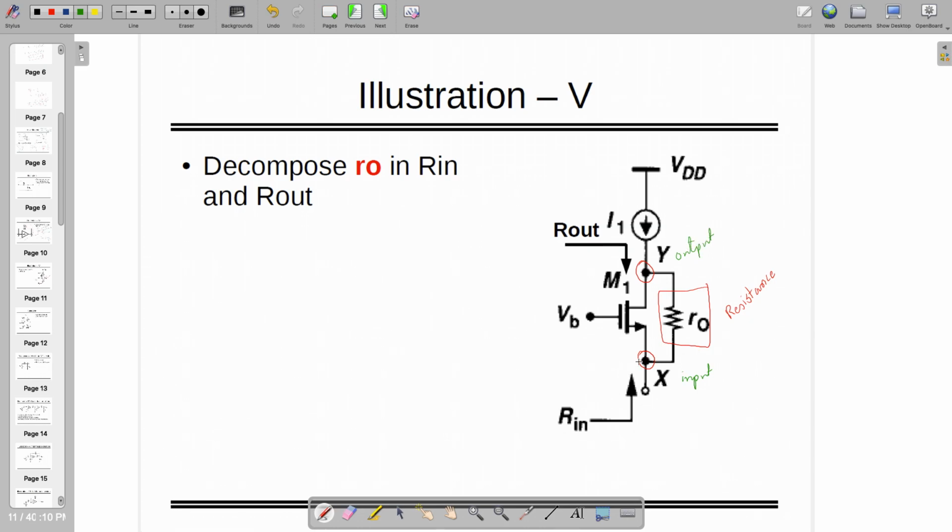So this resistance is going to be decomposed in two parts at low frequency, whose values will be, let's look at our equation which says that Z1 is your input impedance, input side, divided by 1 minus AV, and Z2 is Z divided by 1 minus AV inverse. So replacing these values, what are we getting? Let's call R in and R out as asked in the question.